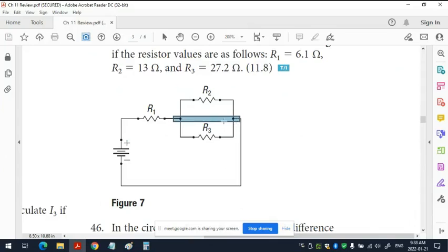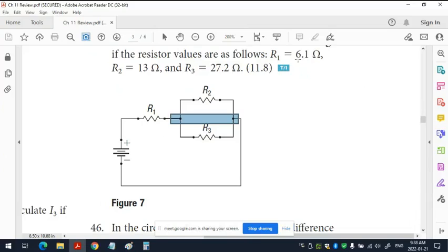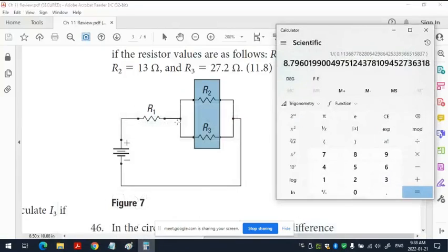Because they're now connected in what? Everyone, look. Do you actually see how it does look like it's connected in series? Because I took them, replaced them with just one. That blue one right there, that thin line. So I add what to 8.79 for 6.1. This is 6.1, and those two have been squished to 8.79. So plus 6 point. So the entire resistance of this circuit is how much? 14.89, or to 3 figs, 14.9 ohms.